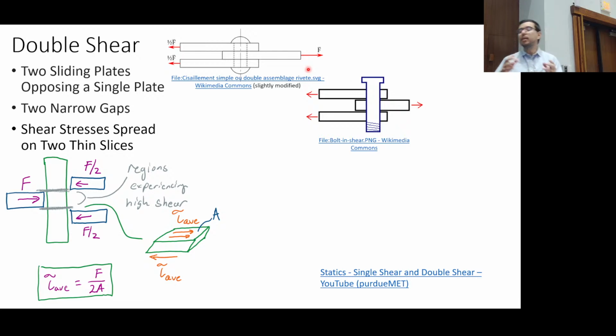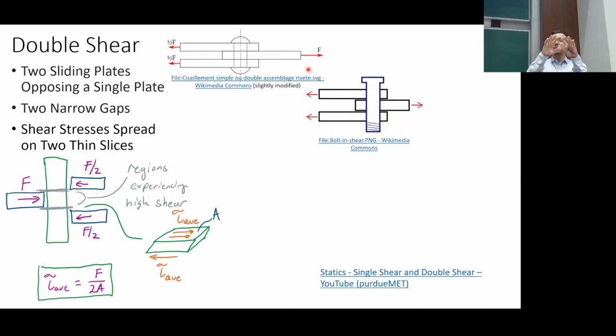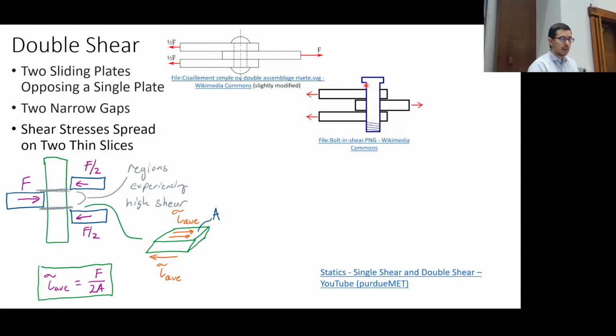And when you look at bolt tightening and stuff, you'll see that there are these kind of rough approximations for the region that is experiencing this frictional contact, or the region that's under compression. Okay, even though the bolt head is maybe right here, and it only looks like it's going here, it actually causes there to be kind of this region that's all under compression that extends beyond.